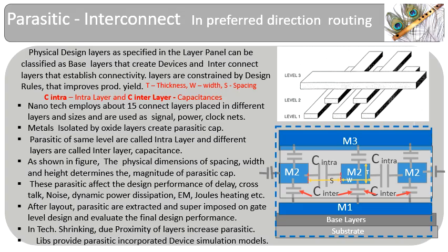After net routing, the extracted parasitics are superimposed on the gate level design and timing performance is evaluated. With shrinking of technology, the reduction of interlayer spacing increases the parasitic capacitances. Characterized logic gates are provided by timing libraries.